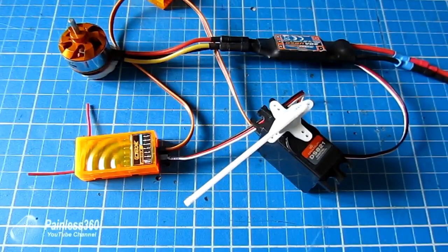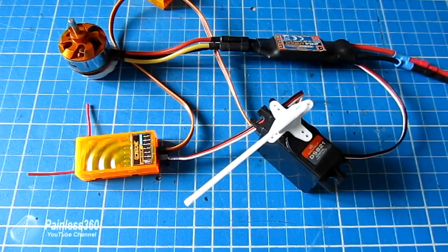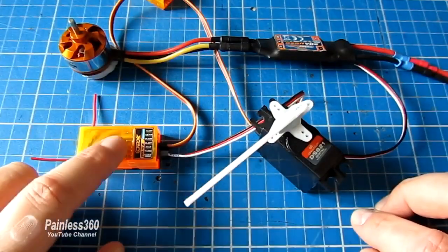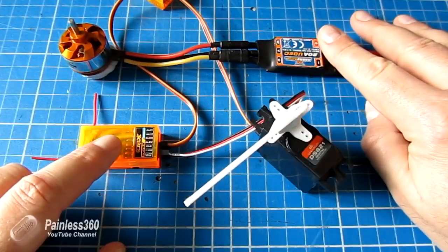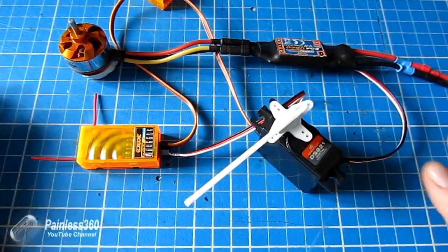We have covered a lot. We have talked about the radios, we've talked about the modes, we've talked about how the binding works, what failsafe is, we've talked about what pulse width modulation is, how that differs from things like PPM or CPPM. We touched on SBUS, and now we've talked about how all the connections work and how the receiver talks to things like the servos and the speed controllers in your model. So hopefully that was enough of an introduction to help you understand the 3-letter acronyms and some of the bits and pieces in the forums that you're going to read.